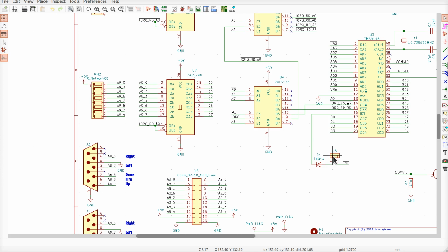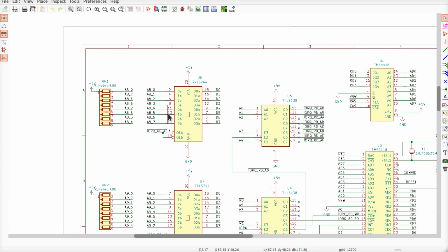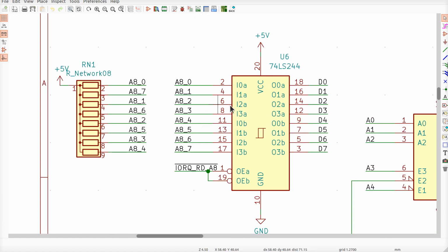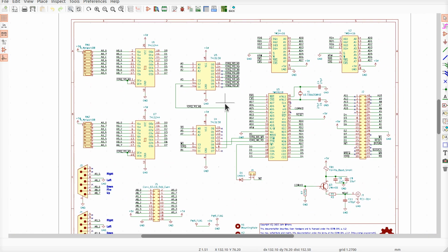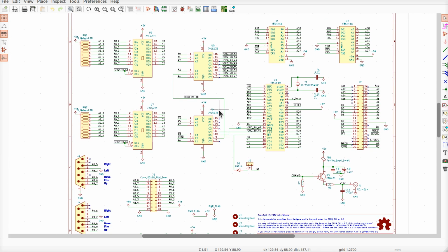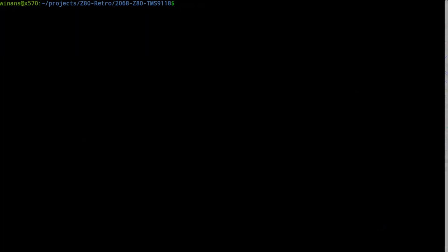If you do this and you jump it over to there, with the diode in there, without the pull-up, it may or may not work the way you want it to, is my point, okay? So if you're going to experiment, put on your learning hat. You're always learning. Don't expect everything to work perfectly all the time, okay? Always beware of every little kludge and hack that I've left on my board. Like I said, I know how to recognize that. So if you're not familiar with this, then just put your pull-up resistors in there. Don't worry about it, because it will work with the pull-ups in there for sure.